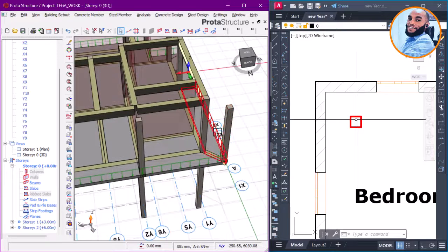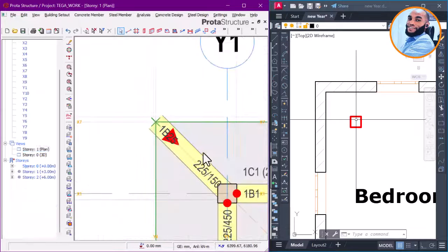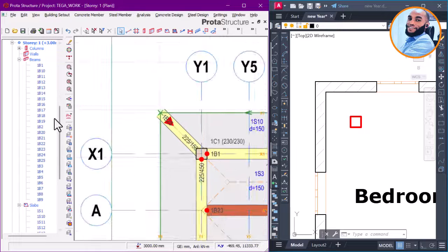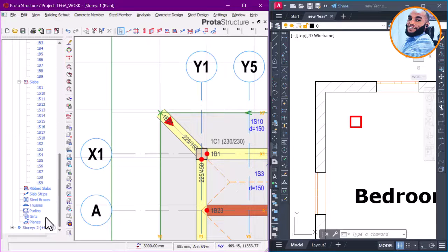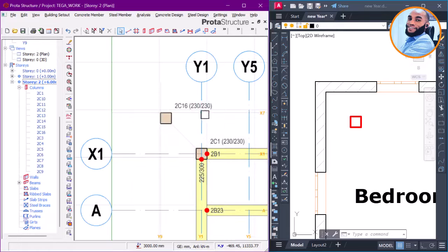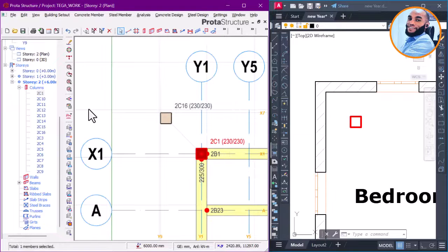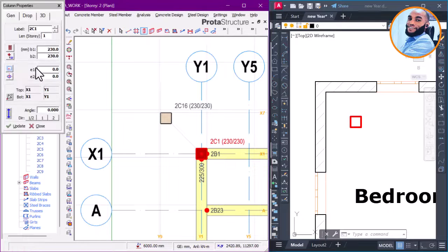The other way that people used to do it right now is to go all the way down to plan view here, and they will have to put one column here, something like this. One column. There are two ways. Let me just show you those two ways. Come here, align column, put a column here, and align again here. Put a column here again. All right.